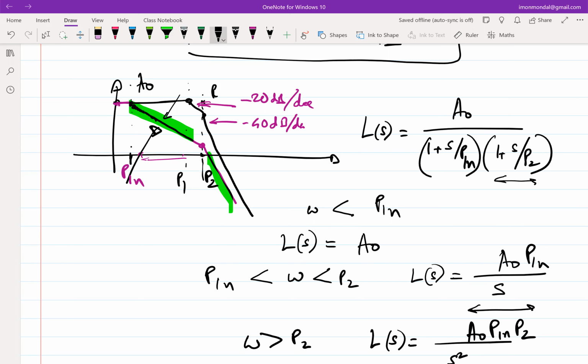So essentially, if you have something like this, let's say you have P1 here, and you have omega u loop here, and you have P2 here. This, to a very crude approximation, can behave like a first order system with a time constant of 1 over omega u loop. And it will not have ringing and all those things. That's the hypothesis. I am trying to convince you that intuitively this makes sense. Does it intuitively make sense before I go ahead and try to be a bit rigorous about this?